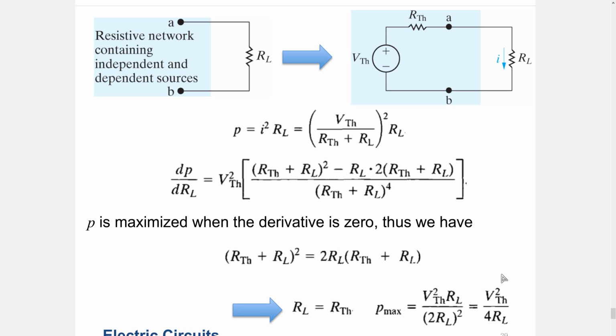And in that case, in order to deliver maximum power, two impedances must be equal to their complex conjugates. That is, RL should be equal to the RTH, just like this, but the reactances should have opposite signs so that they can cancel each other. Because when you have a reactance, that power will be lost. There will be some reactive power that is stealing from your energy source. In order to zeroize it, you need to put the opposite sign